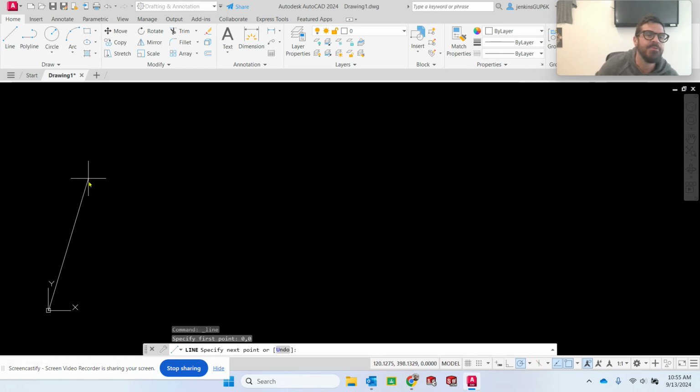I want you to notice a couple of things. I have my settings so that whenever I go vertical, you can probably see a little green line that extends upward from there, even beyond where my cursor is. Even if I'm not directly on that green line, that directly vertical line, it's letting me know that it thinks I want to draw a vertical line, okay?